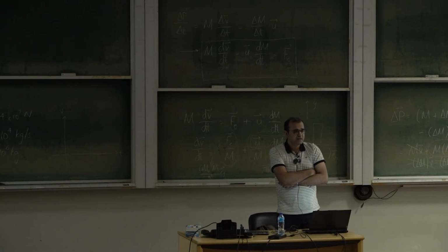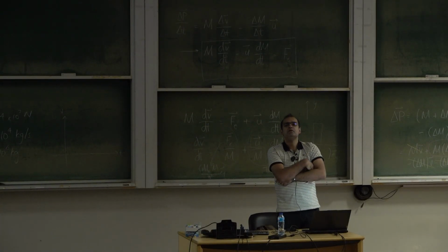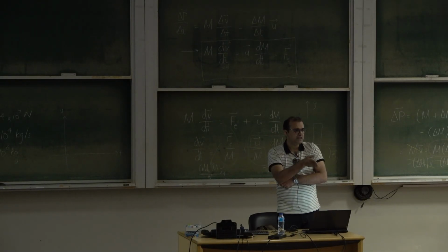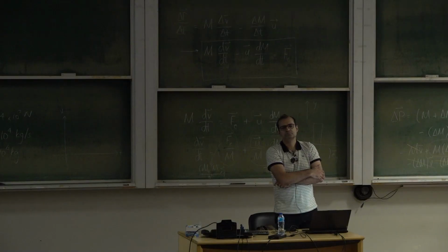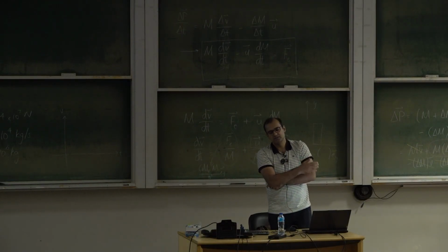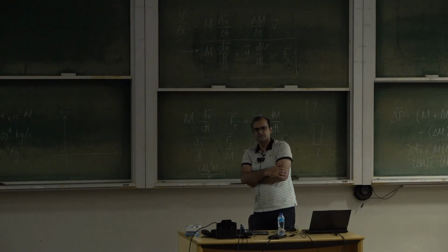If you have a variable mass problem, you do exactly the same thing. Take a snapshot at time t, take a snapshot at time t plus delta t, calculate the change in momentum divided by the change in time, set that equal to the external force. Exactly, yeah. Essentially, yes.